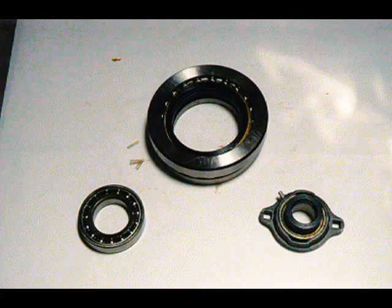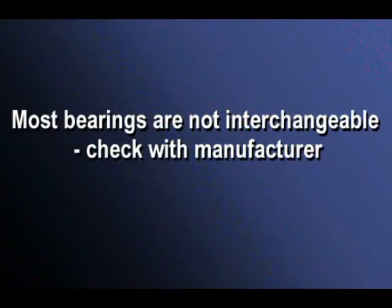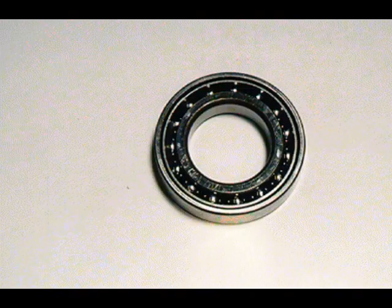Regardless of the type of bearing used within a system, the bearings are designed to carry the loads imposed on the shaft. The important word here is designed. The bearings used are matched to the requirements. This means that bearings cannot be replaced with another type unless recommended by the manufacturer. Bearings are interchangeable between manufacturers. One can get a replacement bearing by using the bearing identification number and matching it with a replacement bearing. The bearing must, however, be equivalent with respect to the inside diameter, the outside diameter, the thickness, and the material. A bearing equivalent catalog is very useful in ordering replacements.